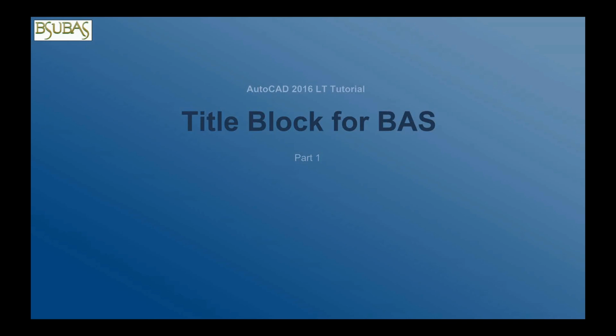Welcome to the first part of our four-part tutorial on creating a title block for vendor-neutral building automation system drawings. In this part of the tutorial, we'll illustrate the use of AutoCAD templates, the menu bar, snap and grid setup, drawing limits, layers, and construction lines.